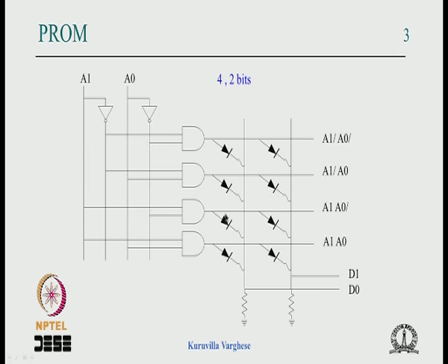So this diode kind of blocks that, so that there is no direct conduction between the VCC and the ground. If this is 1 and this is 0, since this is pulled low, this diode will conduct and the 1 reaches here. But this one is reverse biased; you need to have at least 0.7 volt difference. Being identical gates, that cannot happen, so this will not conduct and will not create a short circuit. That is the idea of the diode.